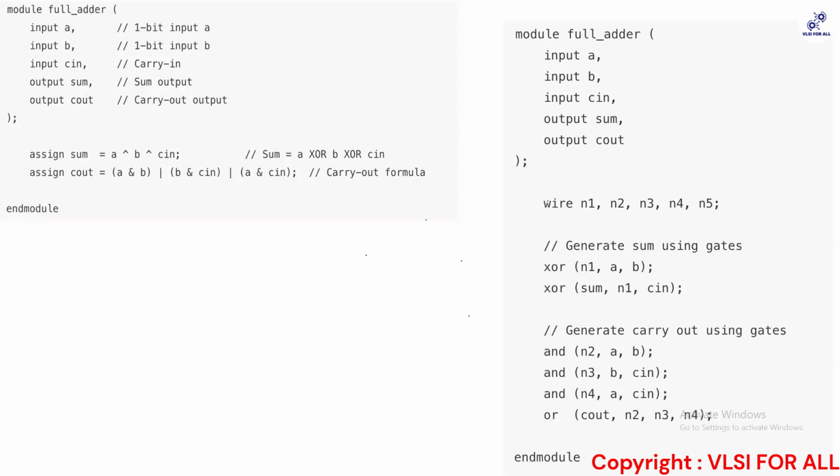Yes. So these are called derived gates, and there is something called a universal gate. So the possibility is that my library doesn't have an XOR gate, but the tool will still understand it. The RTL person can give it in XOR format. He doesn't know what you're going to do. But the way synthesis works, it will tell you, hey man, I can do this function using NAND or NOR gates also. I don't need an XOR gate.